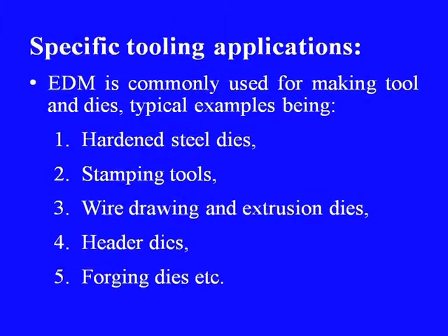Let us see another variation in this EDM process, in which machining with electric discharges in deionized water was attempted. In this process, Kaldeu and his research group have used a new EDM process with polymer carbon electrode material which could be molded repeatedly into complex geometries and used to perform precision EDM machining in deionized water.